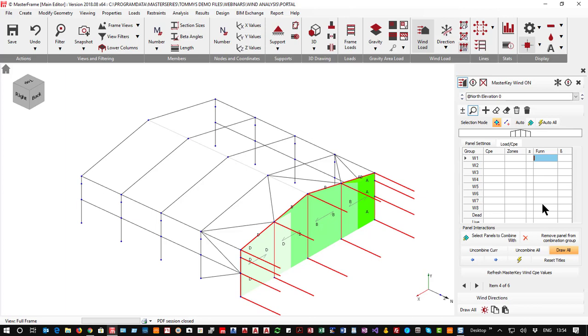There's actually a ratio that you input of B, that width, as against the distance to the other side. Obviously if it's very close, it could be something, I would assume, 0.5. The code will tell you it's either going to be 5 or 0.2. I'm guessing that it might be 0.5, and that'll give you a far higher value of wind when you're blowing down through. So yeah, funneling is not a problem at all.